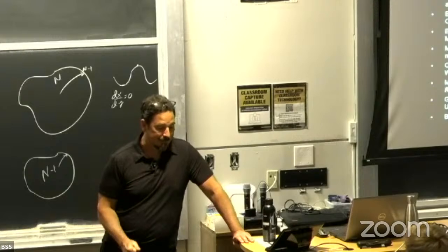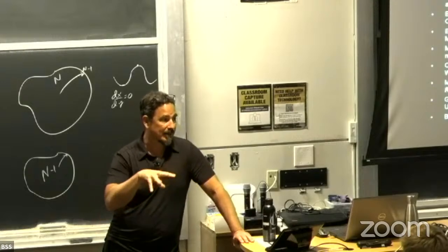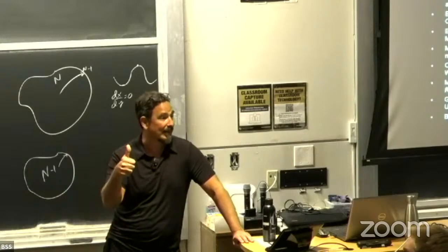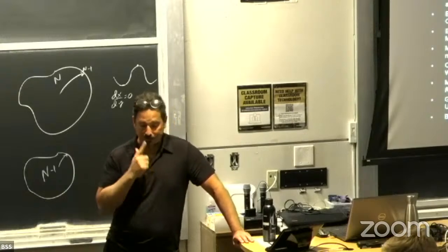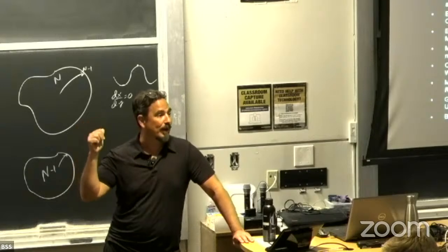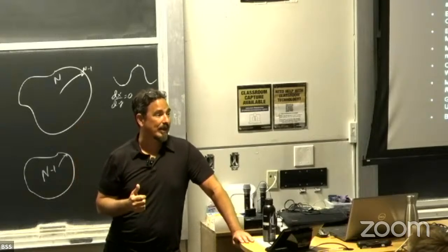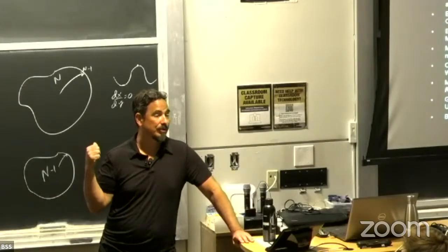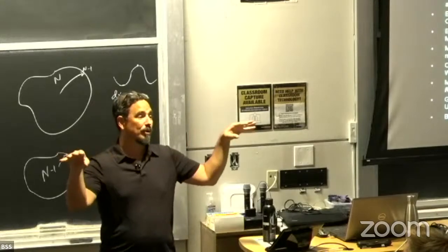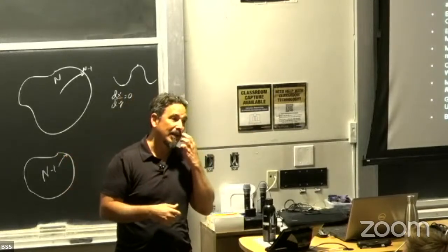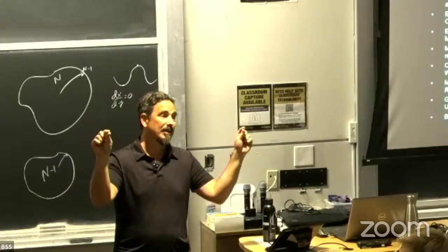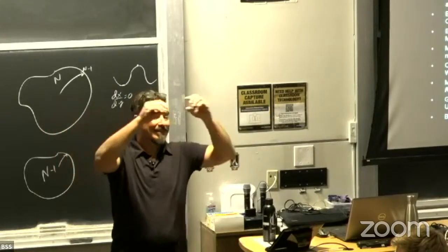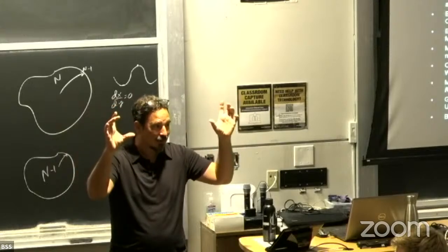Yeah, so the magnetic robots are fairly strong because you can jack up the magnetic field and they'll do their thing. For the electronic robots, we had to develop actuators that could be strong. The platinum actuators that I showed you only do surface adsorption, or if you apply a slightly higher voltage, they oxidize the surface, but only the upper nanometer of the material. So that's the oomph you have to bend the actuator.